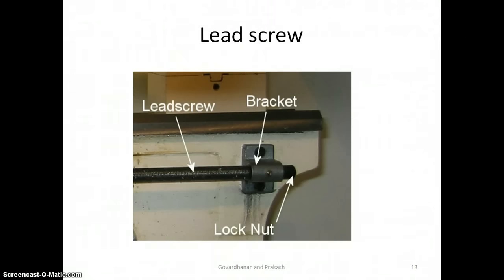When the half nut is engaged with the rotating lead screw, the carriage moves longitudinally. The tool used to cut threads is moved longitudinally in a definite ratio depending on the pitch of the thread required on the workpiece.